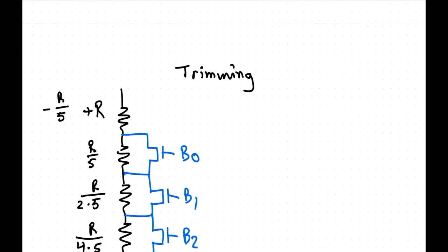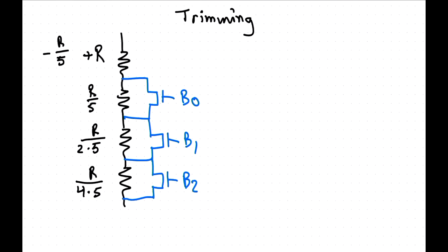If you look at this one here, then the other parasitic for the transistor is the on-resistance. You need to make sure the on-resistance of the switch is much smaller than whatever other resistance you have, so you can ignore it. So you've got to size the transistor accordingly. But that's not normally difficult to do. There's normally plenty of headroom there.